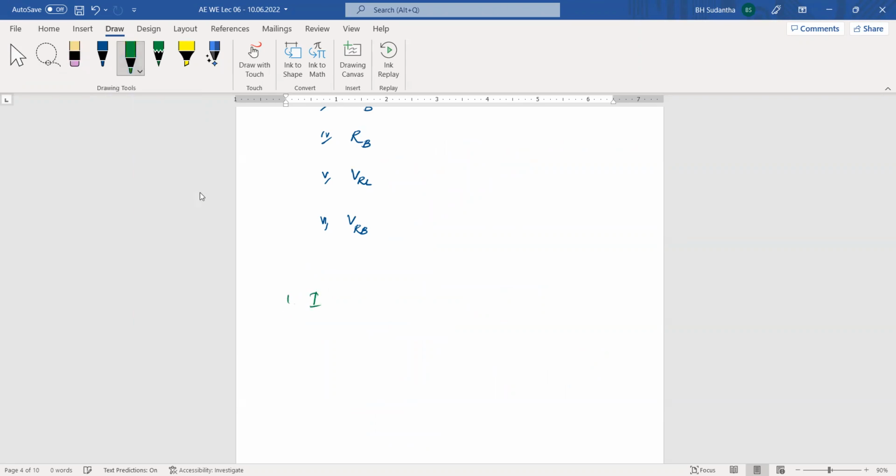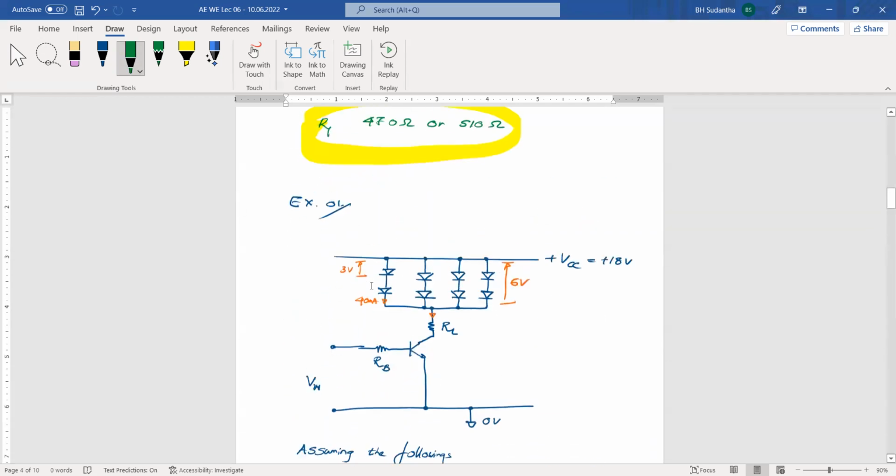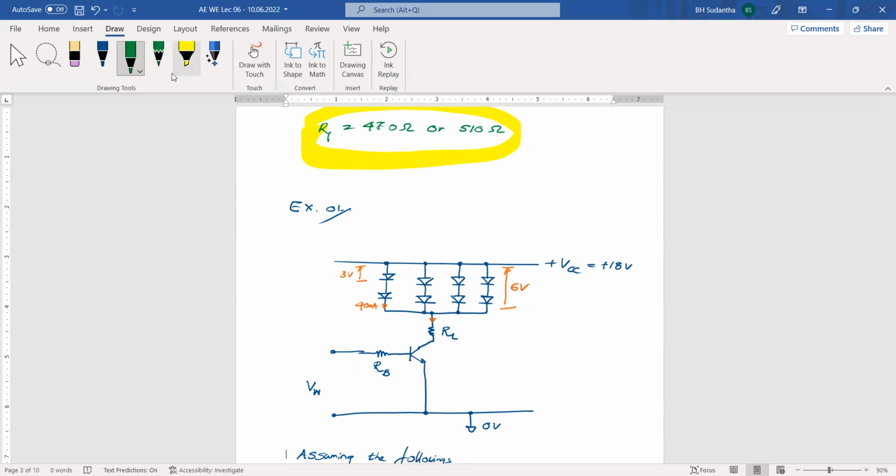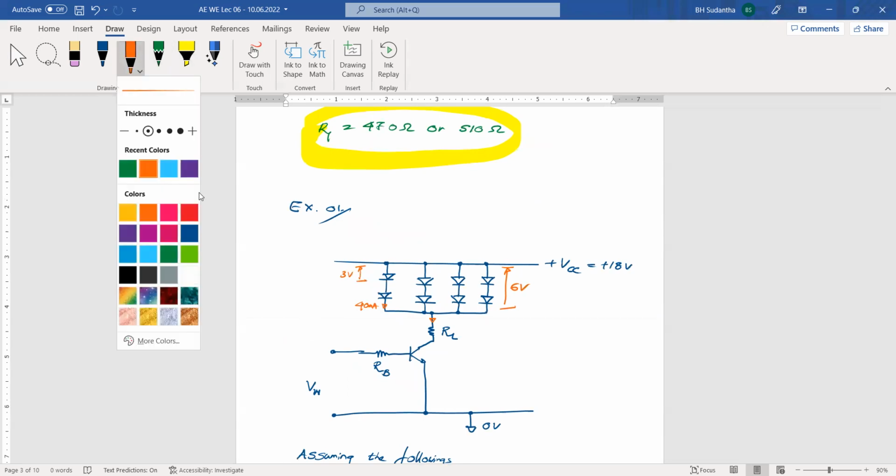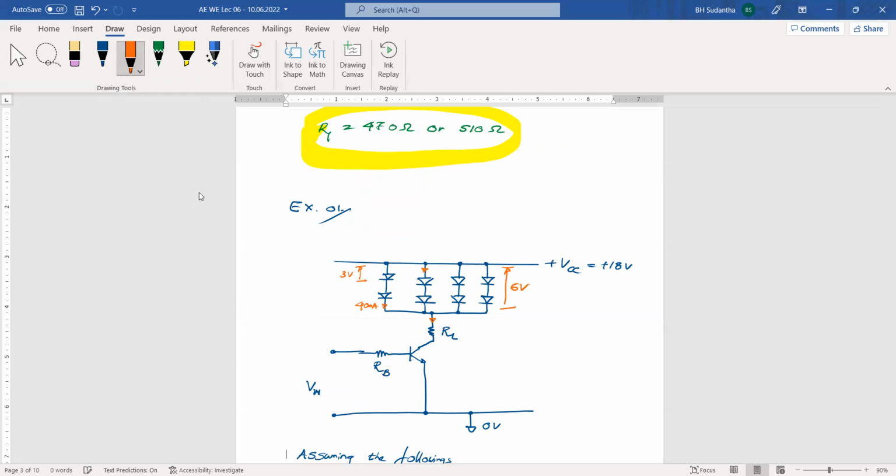IC current is 40 milliampere coming from each LED. Then we have to multiply that, and this is 160 milliamperes. The next one we have to find is from each LED. We have this 40 milliampere current coming through it, but across two LEDs we have 6 volts drop. So 3 plus 3, 6.